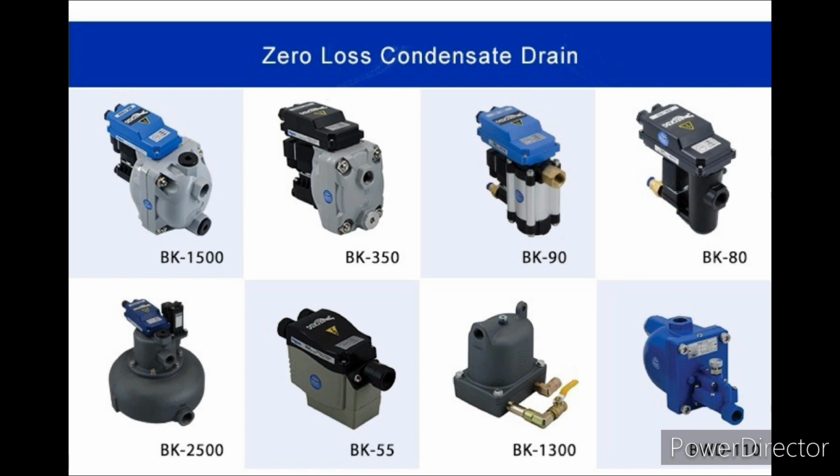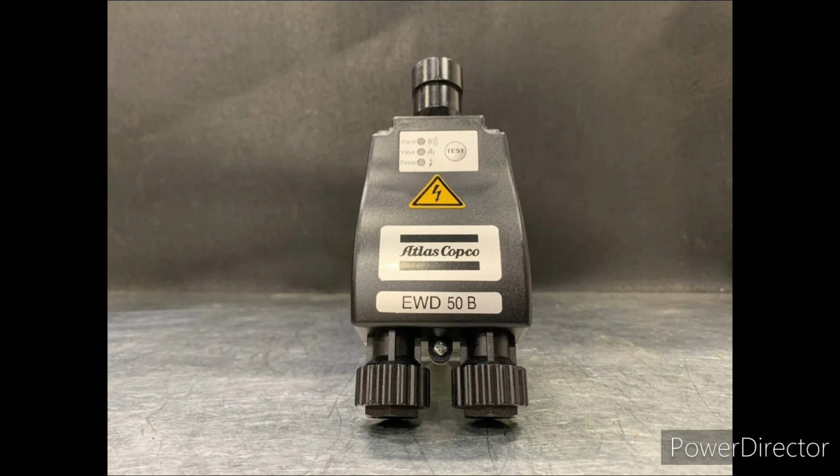Next, function, operating principle. So time to open a valve is calculated based on detection by a sensor. An emergency mode begins after 60 seconds. If condensate is not properly discharged, the emergency mode initiates the self restoration features and the valve is opened for 5 seconds for every 3 minutes, like a time control valve. Temporarily.